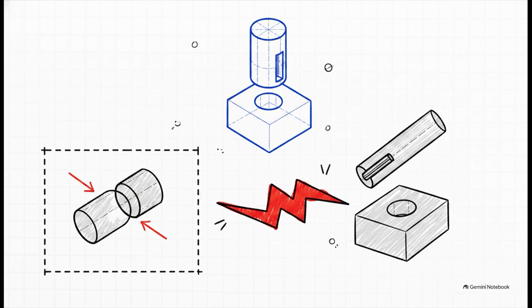They're considered basic, and you have to query them from the 3D model. You must verify that the 3D model geometry, the physical part function, the related assembly drawings, and the 2D annotations are perfectly aligned. Are there missing basic dimensions? Does the model show a gap where the print implies a press fit? Step 6 is where you find those massive disconnects.